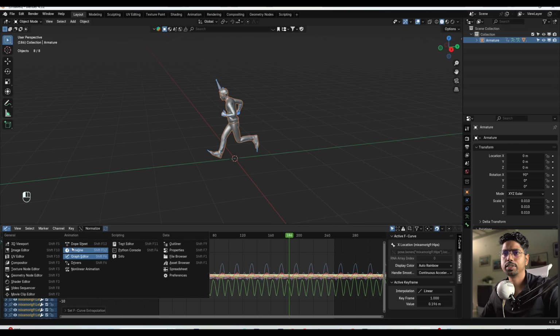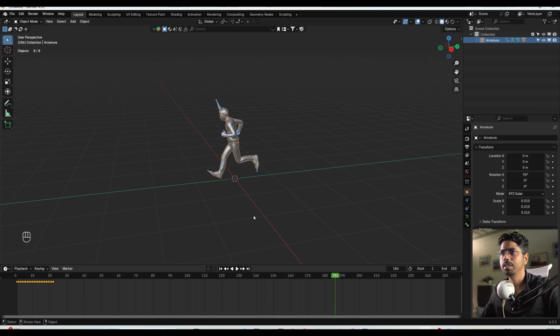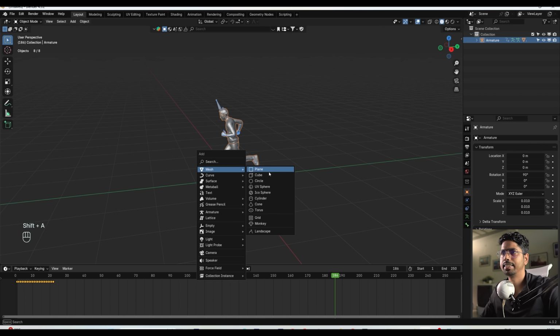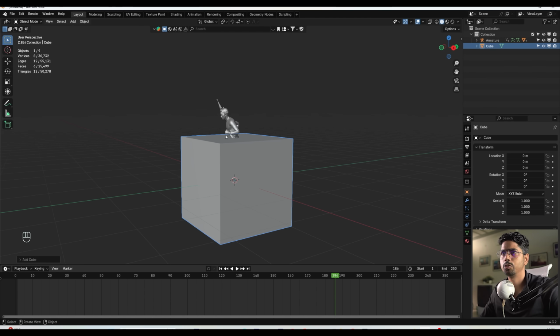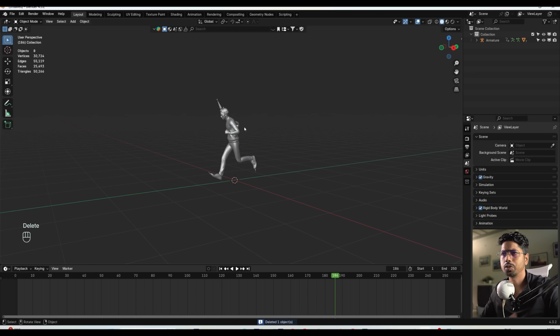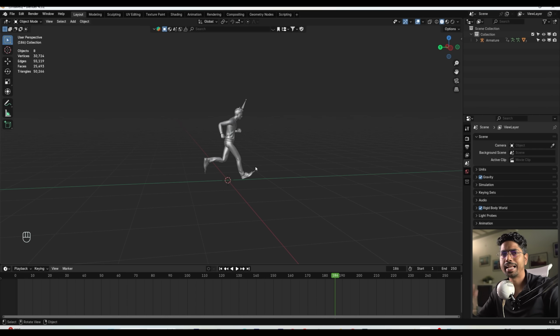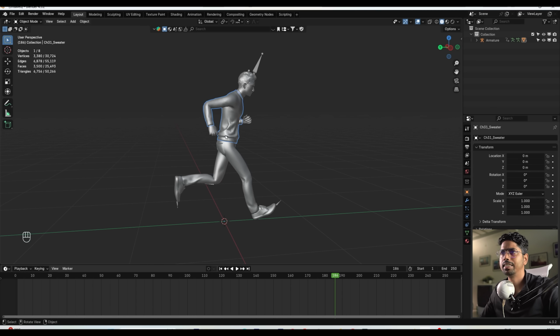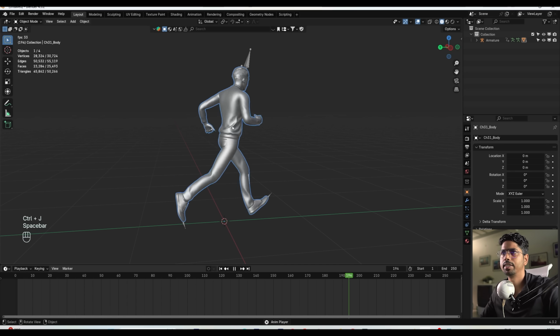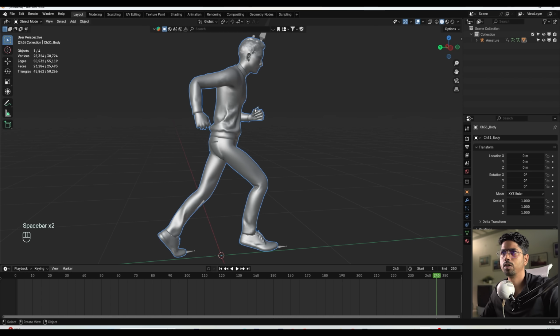Here I'll switch back to the timeline mode, and I'll press Shift A and create a mesh just to check the human size. I guess this is a good size. The next step is to add the smoke simulation, and later we will arrange our scene and I will add the camera and so on. Here you'll see all the character parts are in separate meshes, so I will simply select everything and press Ctrl J and join them. Everything is now one mesh.